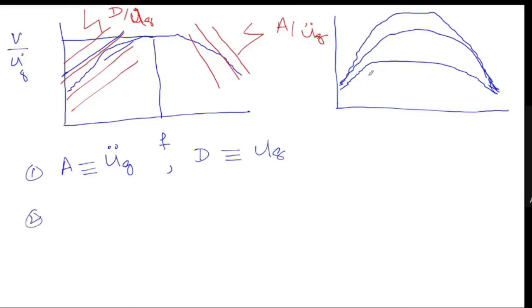Okay, and you can see that these lines are getting closer to each other, so there is no difference between the ground displacement and the structure response displacement. If you look at this plot, it is also giving you a quick view of three regions. For example, this region, then this region, and this region. So this is what is called the acceleration sensitive region. This one is the velocity, and this one is the displacement sensitive region.